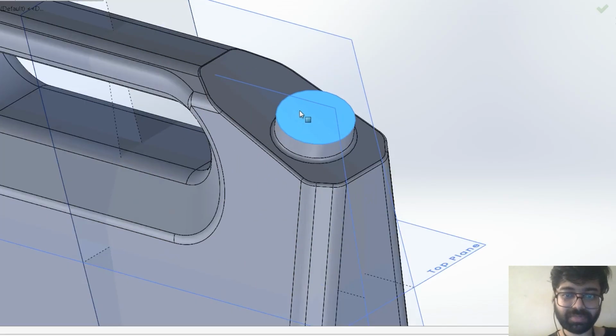So I'll just remove material around maybe 0.8 mm or 1 mm. Actually, 1 mm is very large, it is too large. Plastics are usually maybe around 0.4, 0.2, 0.6 thickness. The largest ones I have seen are 1 mm. So I'll keep it around 0.6 suppose. That also depends on the type of thing you want to contain or store in that. Okay. I'll keep it 0.6. Let's see.